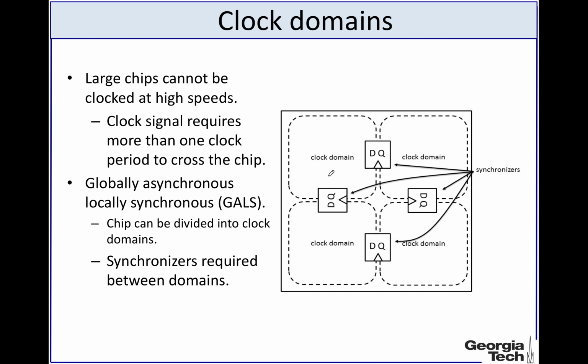its own clock signals. The frequencies can be the same but their phases may not match, and the way each of the clock domains interacts with the other clock domains is through a synchronizer, and this synchronizer tries to make sure that no timing violation occurs when these clock domains try to interact or exchange data. So we will look into the synchronizer in the later part of the video lecture.